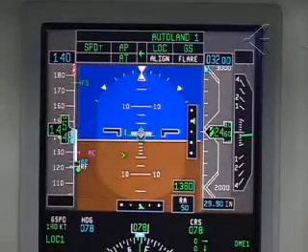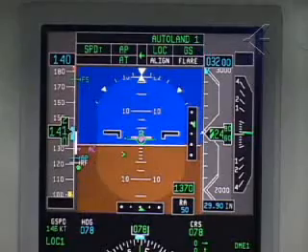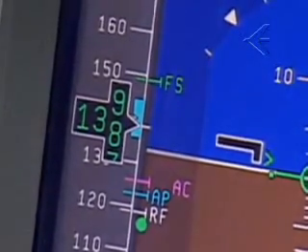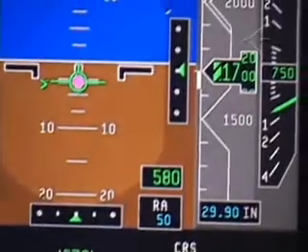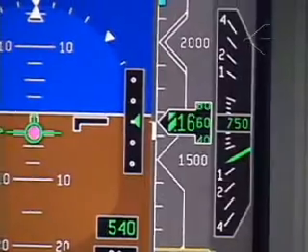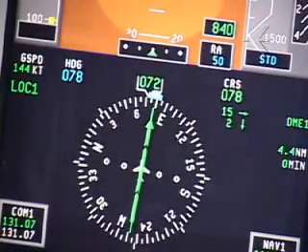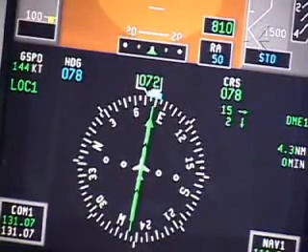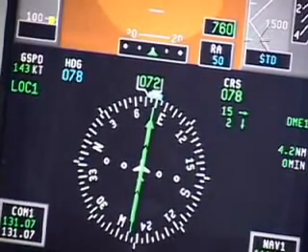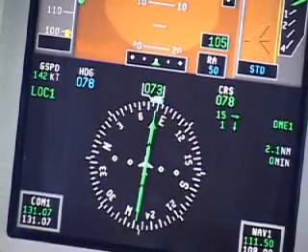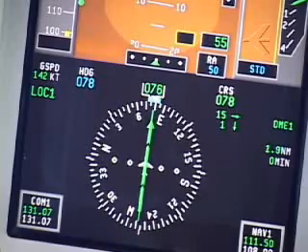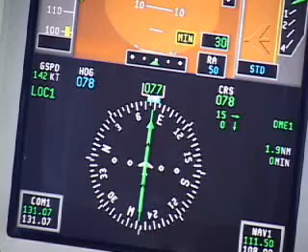Follow localizer and glide slope tightly in a stabilized flight. Monitor airspeed closely too. Rate of descent will be consistent with the glide slope beam angle. During final approach, the parallel rudder system logic applies a crosswind landing compensation until 150 feet. Below 150 feet, the align mode is engaged and a decrab maneuver is performed to align the nose with the runway heading.